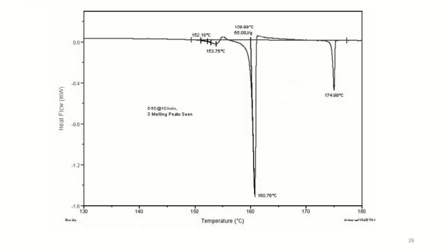So it means that the heating rate of the sample is quite important. It would help us to determine the right information for the right applications of any drug or any material, while it can interrupt the data if the scan rate is quite low compared to the optimum.